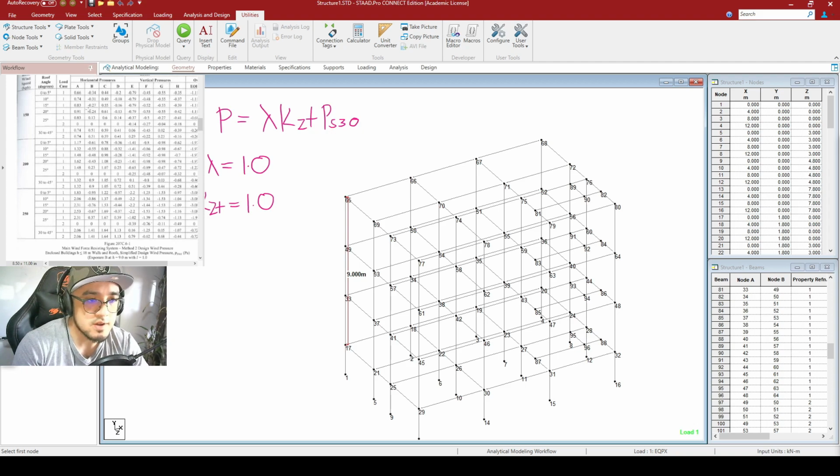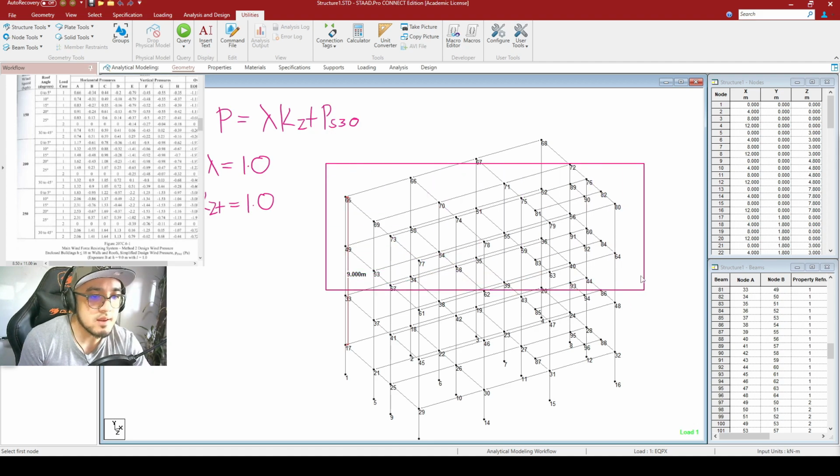So first things first, let's solve for the roof angle in degrees and the basic wind speed first. As you can see from this particular example, it is stated in the previous pre-recorded video lecture that our building is to have a roof deck and not a sloping roof or a monoslope roof. So meaning, guys, that in this example, our roof angle is to be 0 degrees since our roof is to be horizontal.